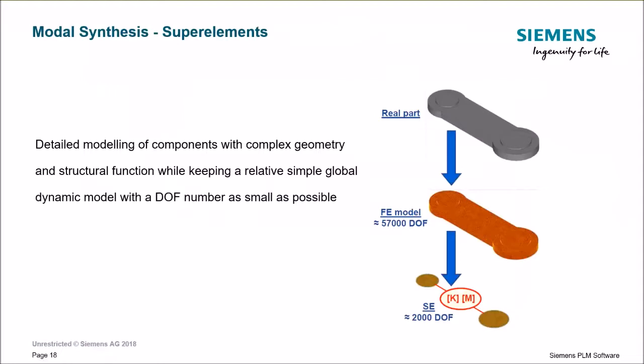So I'm going to give a little introduction to the meaning of defining flexible models. In this case, typically, if you want to introduce explicit finite element modeling into a multi-body analysis, it is going to be too costly, because the number of degrees of freedom in typical FE models is too large. And because you are solving nonlinear equations of motion, it's going to take too long. It's going to be too expensive. In that case, you need to apply a so-called model synthesis to reduce the number of degrees of freedom, but to keep the structural behavior of the part